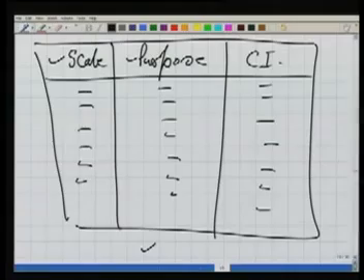So this table can help us. If I am working for town planning, I am going to make a map of 1:500. What should be the contour interval? I am going to use the contours for drainage network planning. What should be the contour interval? So these tables will help in that sense.